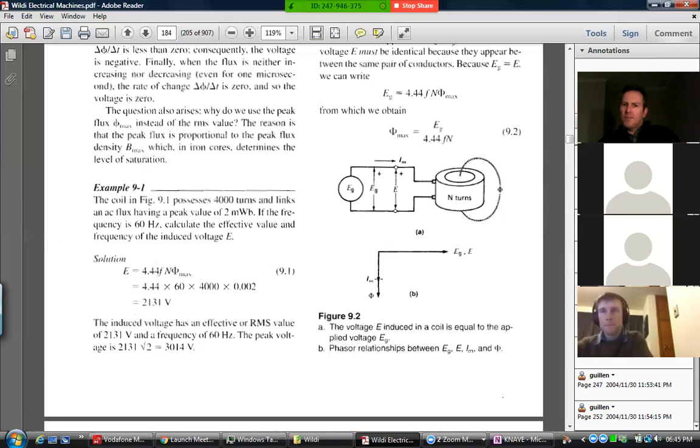It's in the same orientation as the flux, because what produces a flux? It's the amp turns. Flux is produced by amp turns. So as amps run in your circuit, so flux is produced in your circuit. So the magnetizing current that produces that flux and the flux itself are the same. They're 90 degrees compared to, we take this as the reference, the supply voltage.